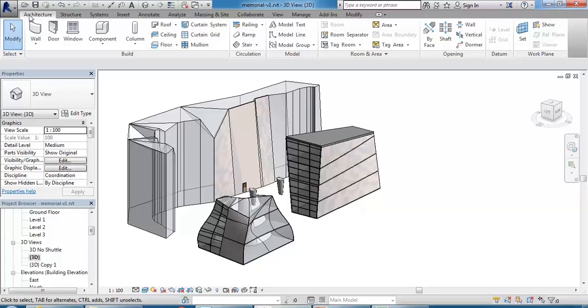Okay, there's a few tricks. There's a few different formats that have different advantages. So you can use the DWG format. Generally, that works pretty well, but it just won't cope with some geometry. So if you try DWG first, let me know if it's not working for your geometry, and then I can show you a couple of other formats that will sometimes work a bit better. But DWGs work pretty well because AutoCAD format's a pretty strong all-round 3D format. So that's possibly the way to do it.